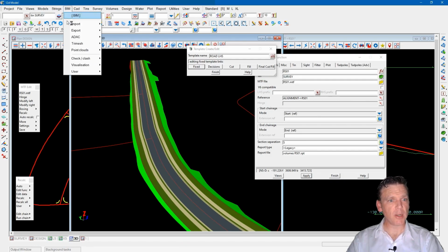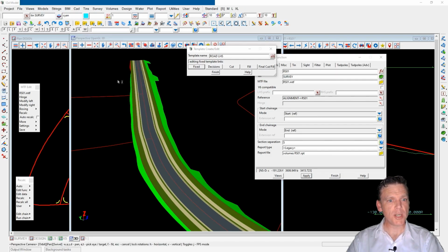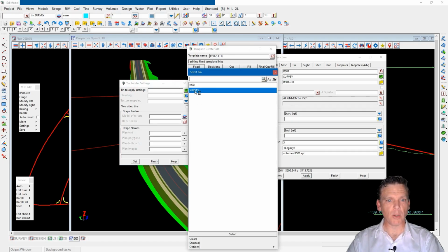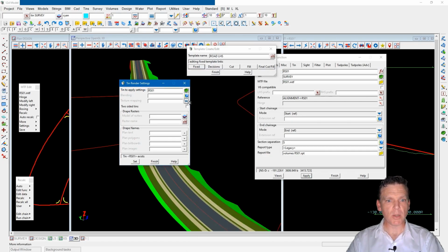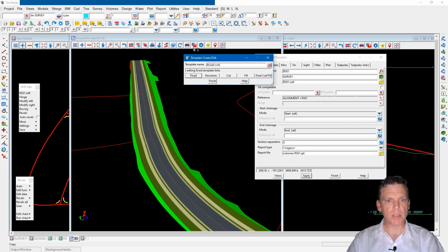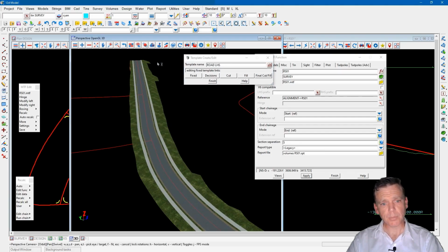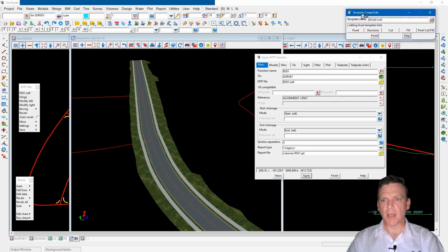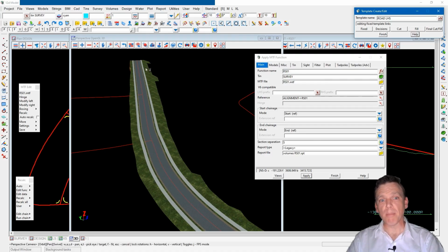And if you wanted to get a little bit fancy, we could even come in and render it, and essentially applying little bitmap files based on those colors. 12D has a textures file, simply set that, and we get quite a clean result straight away, where grass starts to look like grass and the bitumen is starting to look like the bitumen, just based off the colors. So that's happening automatically in the background the whole time.